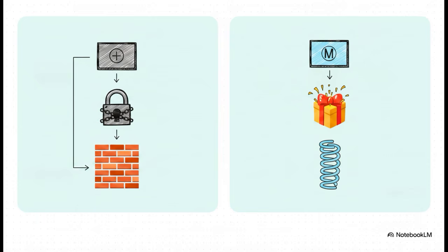The rigid frame means you get exactly 0.25 millimeters of position tolerance no matter what. But the frame with the MMC modifier gives the machinist flexibility. It fundamentally changes how you fixture and inspect the part. It's one of those rare times an engineer actually makes a machinist's life easier.